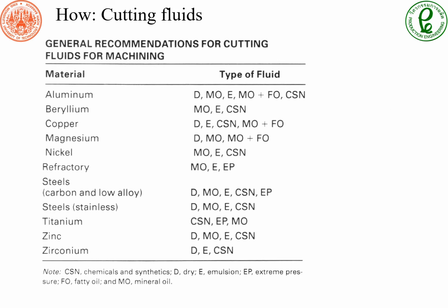We also have cutting fluid. As I mentioned earlier, we try to always use some kind of cutting fluid to relieve the heat on the workpiece. It can come in many forms. There are some synthetics, and there are some oil-based cutting fluids. This cutting fluid not only relieves the heat, but it also helps in flushing out the cutting chips remaining on the workpiece. These cutting chips can sometimes cause some damage on the workpiece. So by providing the cutting fluid, we are making the process smoother.